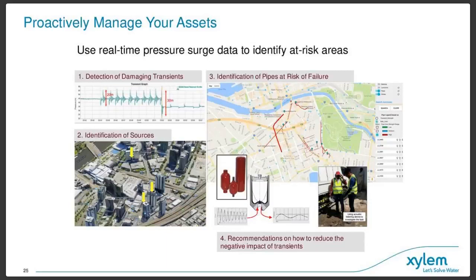If we take the pressure transients, for example, pressure transients are a contributing factor to the eventual failure of pipes, among other factors. But if a pipe is seeing very sharp pressure changes of large magnitude very frequently, that is a good indicator that there is excess stress on the network around where the sensor is, and so the network is not calm.